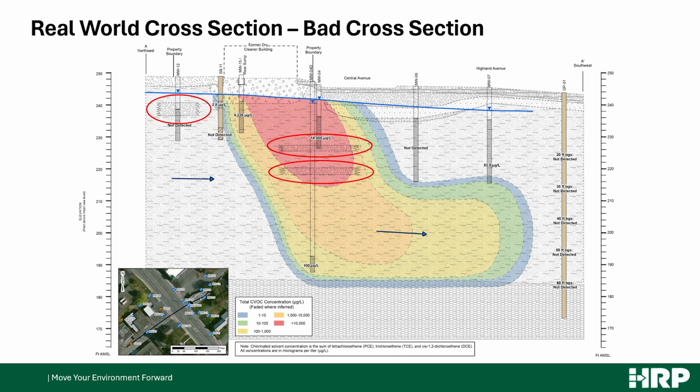Typically, your groundwater is going to be affected by higher or lower conductivity layers in a specific way. In this sense, they didn't show that happening. So these layers don't have any added value in the understanding of the contaminant transport. There's other issues with this cross-section, including this entire lobe of contamination that they have in the subsurface was needed to fit their model instead of looking at the data and making a model fit the data. They have a slight detection in this well, and this well was non-detect, and so they had to extend their plume about twice as far as they should have to just touch the bottom screen interval of this well, and it doesn't represent an accurate depiction of the subsurface. And when we sampled the site ourselves, we came to a much different conclusion and also a different remedial strategy.